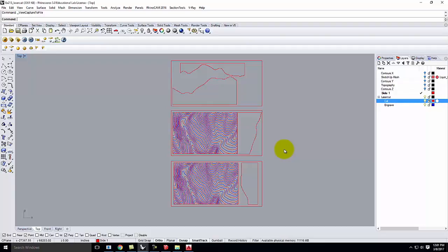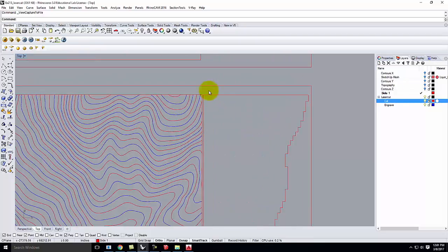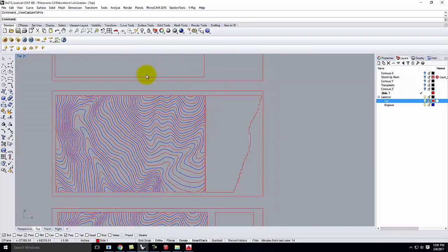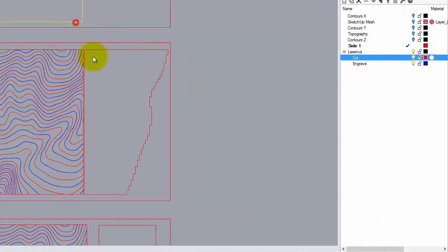Oh, and just remember, there's one other piece of this. These sides are exactly the dimensions of the 11 by 17. Well, the cardboard has a thickness to it. And so if we were going to glue these 4 sides together, when we butt the joints together, we'd gain distance.